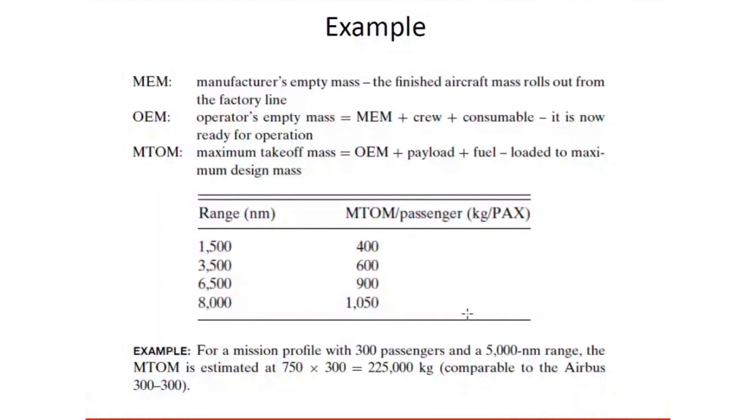You'll of course be using different techniques for weight estimation, and as and when you choose some component, let's say you've chosen your engine and you know that engine's weight, that adds to your accuracy. And you also have the fuel weight that also will improve your accuracy. So as you progress in the design, your weight estimation will become more and more accurate. Initially, you start with rough estimates like what we have seen here.